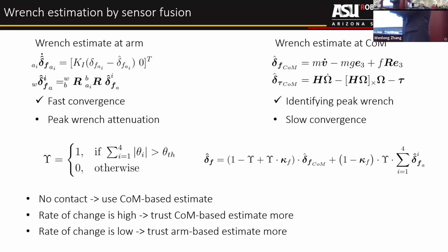Of course, there are tuning parameters you can see, but that's something we're doing by leveraging the sensors on both the arm and the center. The reason behind this is that right now it is not a single body, it's a multi-body system. You have the centerpiece here, and you also have multiple other bodies, so you can run these wrench estimations in different bodies, and that allows you to do this sensor fusion. You can't do that with a conventional fixed-body setup, where everything is supposed to measure the same thing.